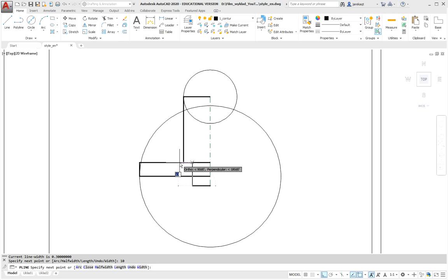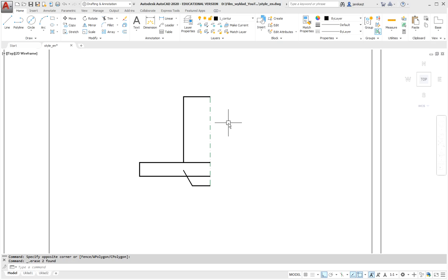And now we want to draw at an angle. We use the relative indication or shift key at 10, and now we must separate it with a minus sign and 120. We have an outline. These circles were just for me to point this point and this point. We no longer need them, we can remove them.